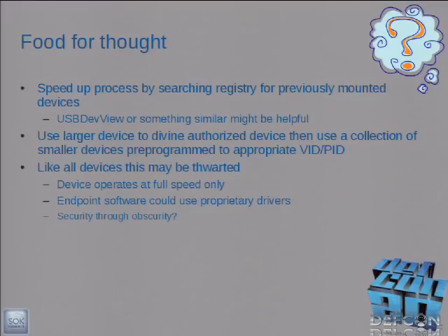One other thing: who remembers what's the maximum packet size for a full speed USB endpoint? 64 bytes. What is the default block size? 512. So what happens is it has to fragment and unfragment all those blocks. That does give you a little bit of a performance penalty, unfortunately. But I don't know how you could do anything better other than find something that supports full speed.